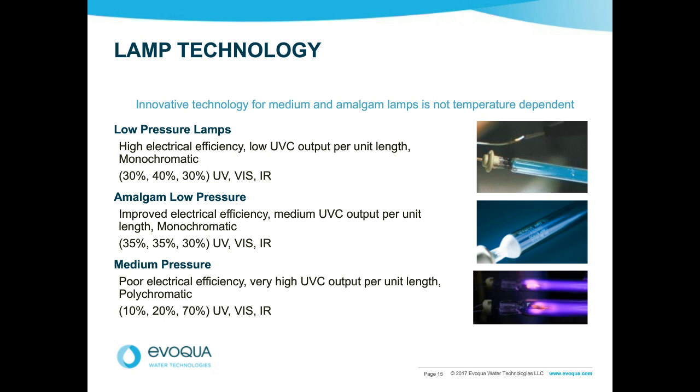Can I use a UV-rated 185 nm, which I'm assuming is nanometers, but I'm not 100% sure, for TOC destruct? Okay, good. For TOC destruct to also be effective for bacterial control, or do I have to have a 185 nanometer for TOC destruct use and a separate 254 nanometer UV for bacterial control? This is on an RODI water loop.